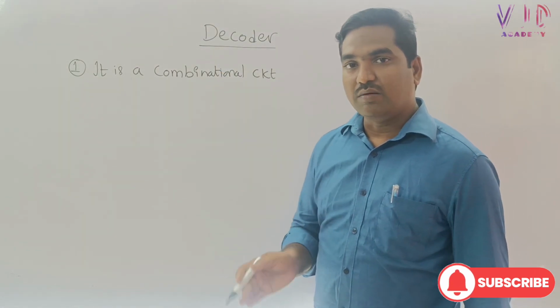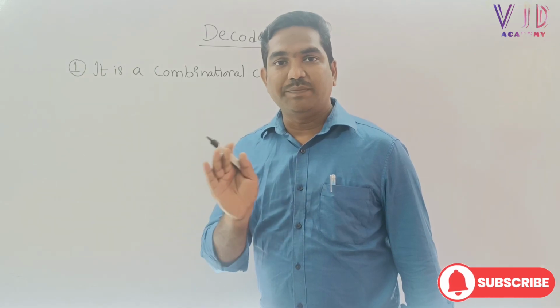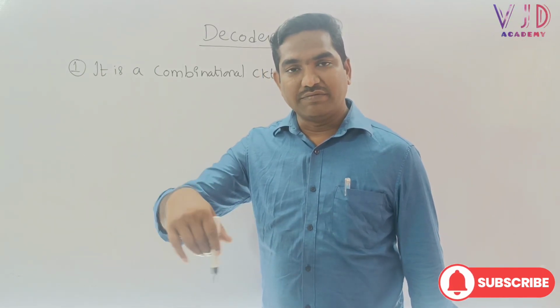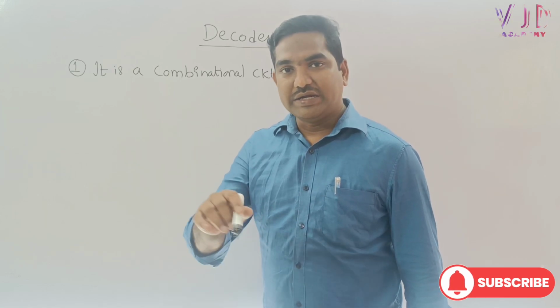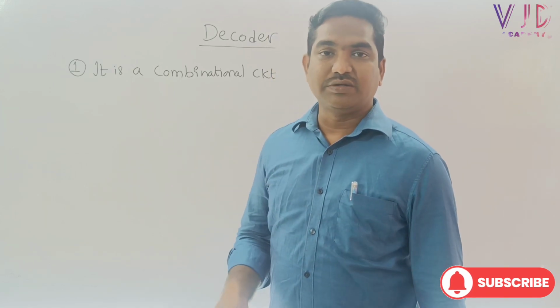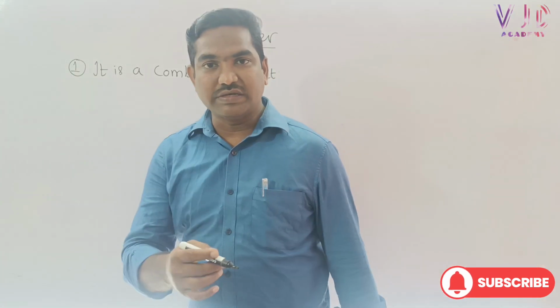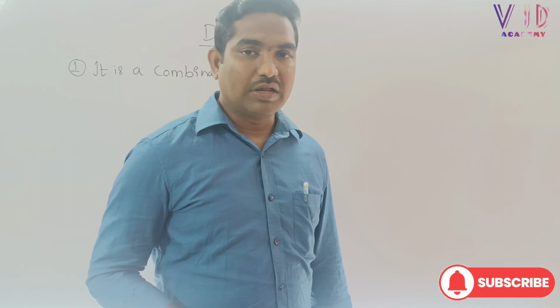The moment I say combinational, its output only depends on its present inputs, and it should not have any memory, it should not have any kind of feedback, and it should not contain any synchronization process. So that is the thing about combinational circuits. All these things are applicable for decoder also.